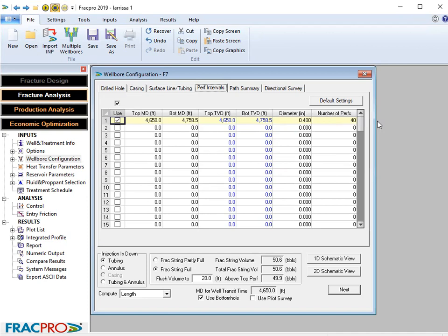because what they are doing is they have to burst the pipe, the casing, so that fluid can easily flow. So they send in maybe explosive, some kind of a gun that is shot. Remember, a gun is made up of bullets. So it's not just a continuous perforation. Within that interval of perforation, you have produced small holes. It's not as if you have just destroyed the whole of that zone and the fluid is just flowing. No, we have holes within that zone where fluid can easily flow. So this number of perforations now represents those holes.